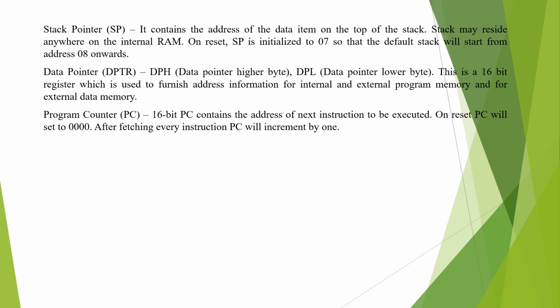We can manually set the starting address of the stack by programming, and on reset the stack pointer is initialized to 07 hex, so that the default stack will start from the address 08 hex.